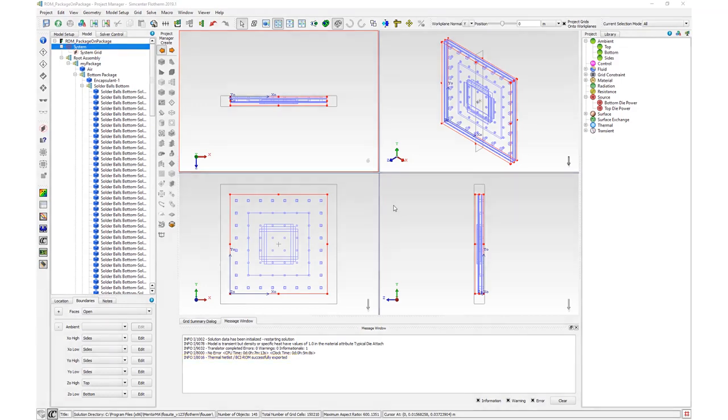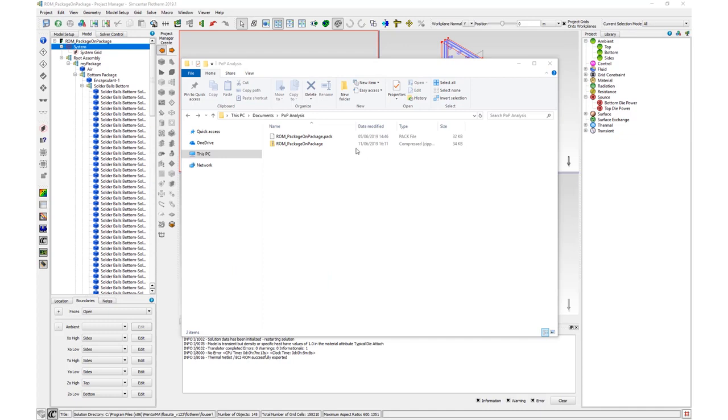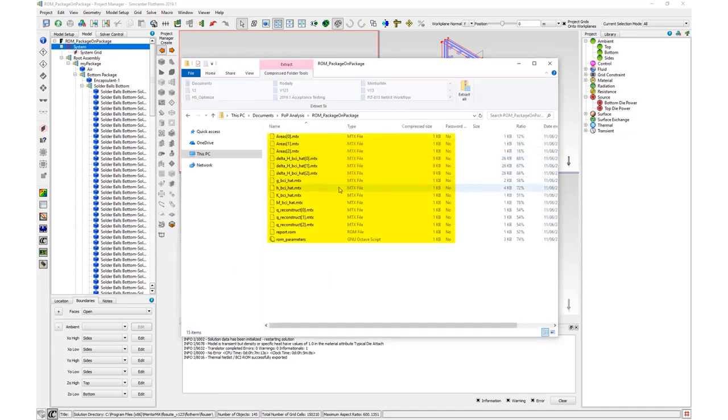The reduced order model is exported in the form of a zip file which contains star.mtx, matrices defining the ROM, report.rom, a brief report of the result of the extraction process including achieved relative error, and rom_parameters.m, a script compatible with mathematical programming tools such as Matlab and GNU Octave that provides a means to set variables of interest when solving the BCI-ROM in these tools.